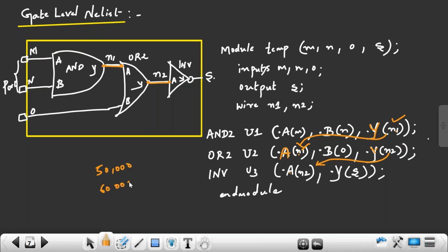Why are we doing it with less cell count? Why not with a high cell count? I told you, one command will take 2 days. See, my recent run was 11 hours for the first command, first step. So I have like that 15 steps to be done. So one command is taking 11 hours, so you imagine. For that reason, we work with lesser cell count, which means the runtime is less.